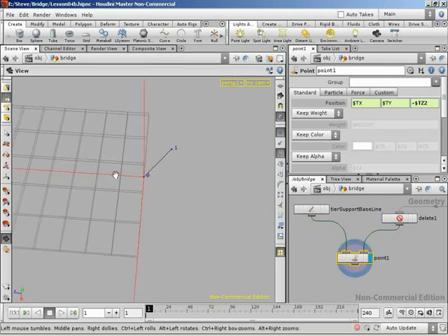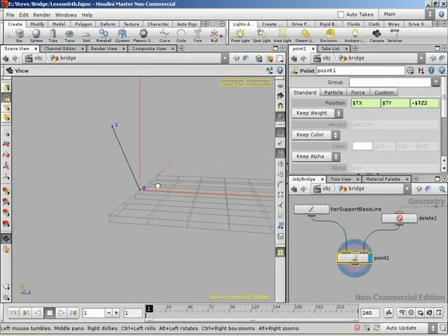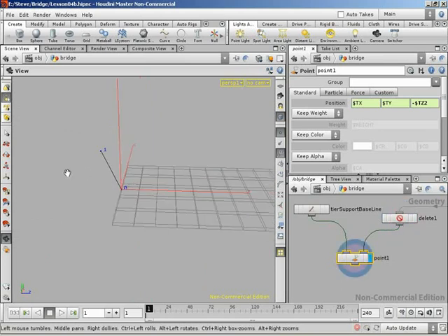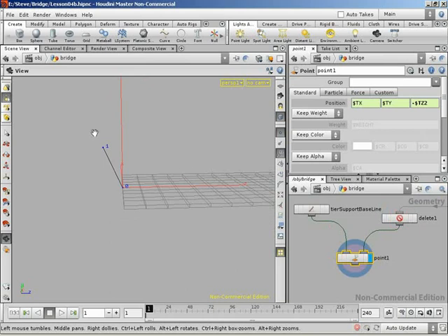So our line comes in, and its position Y and X stayed the same as before, but its position Z of 0 is taken from the position Z of the 0 point coming in from this delete node, which was at the origin, and its position Z for point 1 is the inverse of this position Z. The reason I've gone with the inverse is just the way that we're setting this up. Could have gone either way, but I've chosen to take it this way. I'm then going to shift everything along when it's copied and ignore this first point when we copy. If we'd gone the other way, we just ignore the last point when we copy along. So it's just basically a matter of preference with which direction we're taking that.